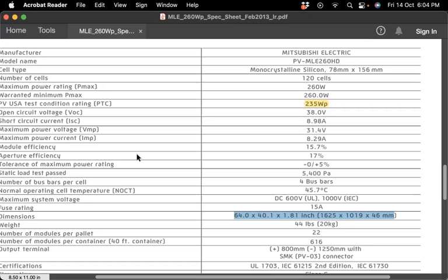However, for example, whenever you are implementing solar cells in Cairo, humidity is not a big factor. Maybe dust accumulation is more important. So of these 5 parameters, 2 of them are very major everywhere, irradiance level and temperature, and 3 of them may fluctuate from one position to another, depending on your selected location for a solar cell.